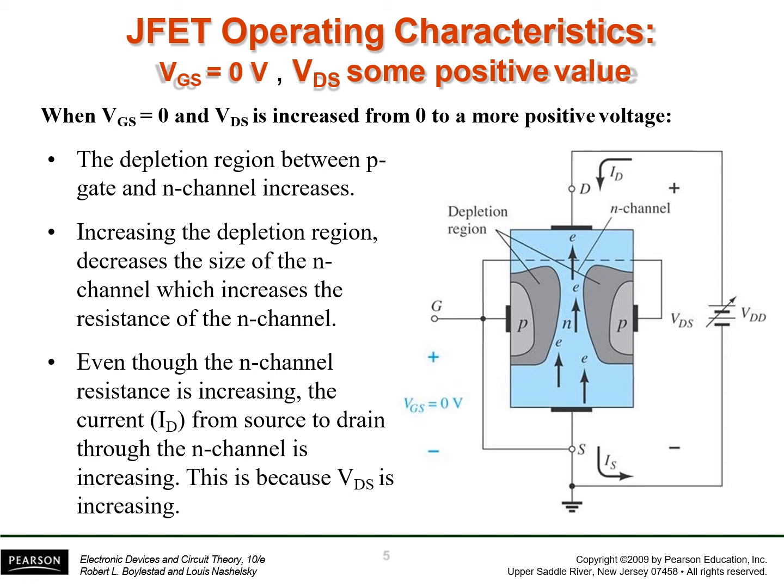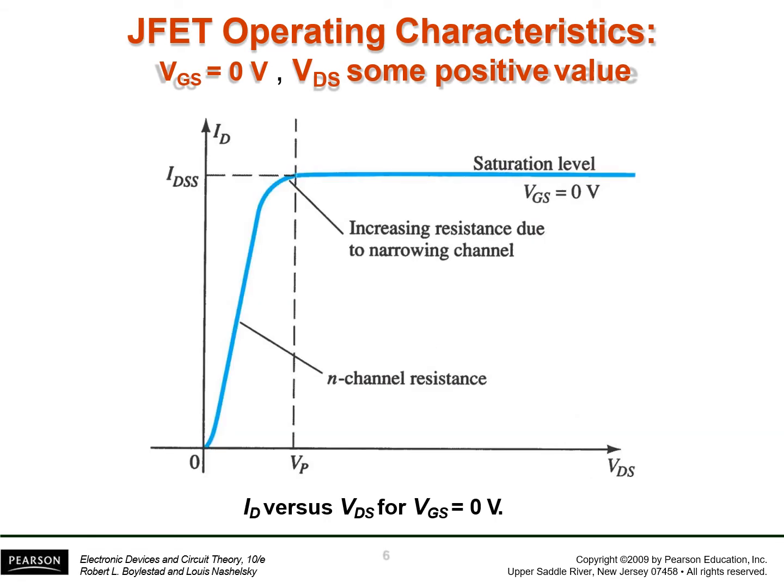As we go on increasing it, the current through it increases, and the depletion regions on both of these ends keep on increasing, and a point comes when both of these depletion regions are connected to each other, thus blocking the path of further current.